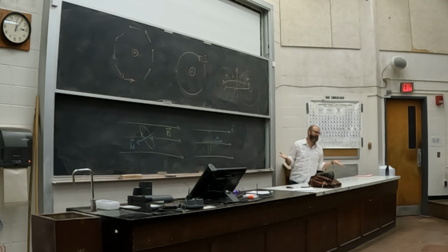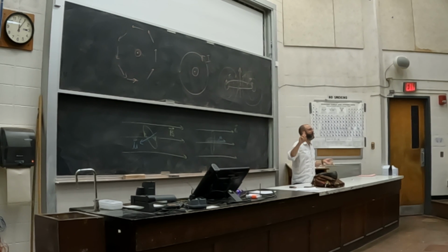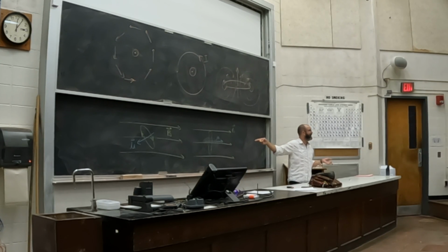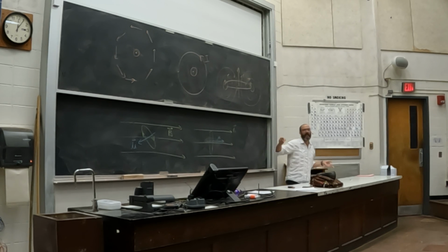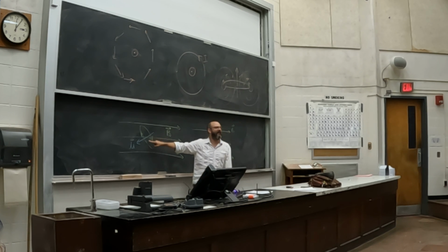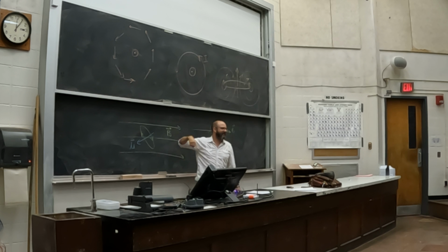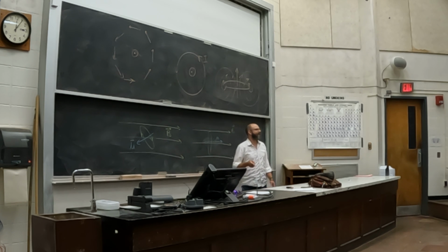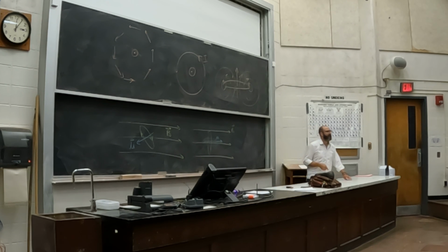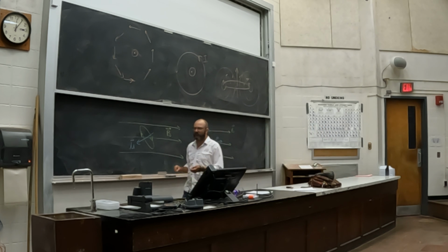AC motors work differently. We don't really talk about AC here, but if you know anything about AC, you know that the direction of the current goes back and forth. If you flip the current direction, you flip the magnetic moment, right? So every half cycle, this guy just changes direction, and you get continuous rotation. Okay? So this is how a motor works. There is a torque produced here. The torque,